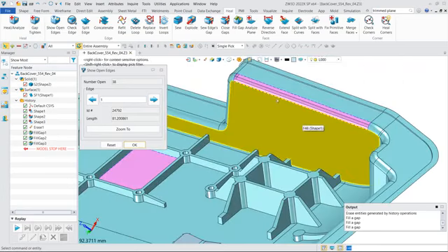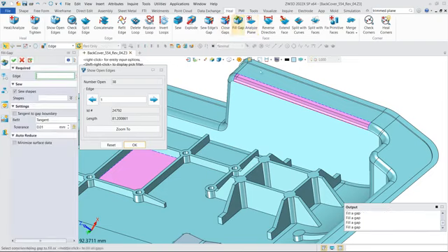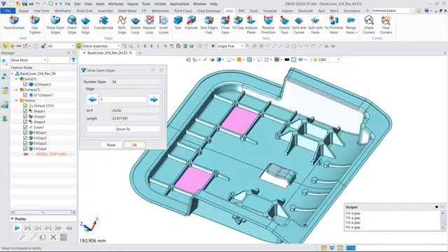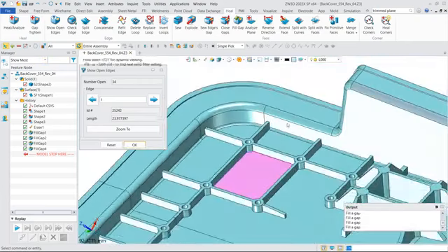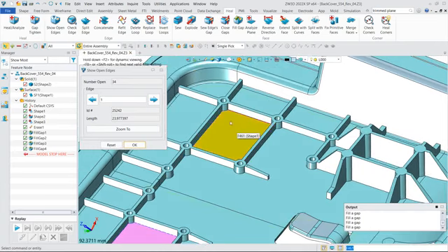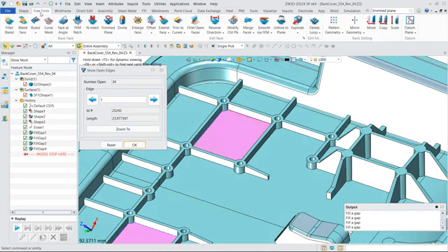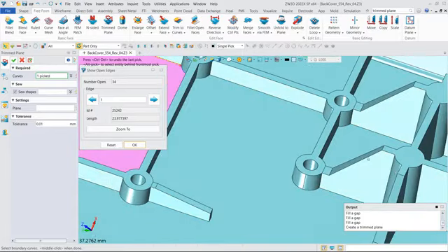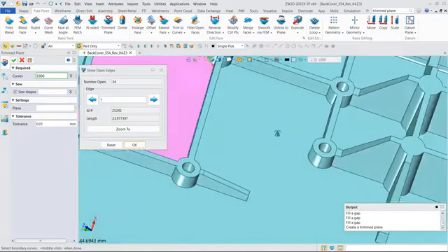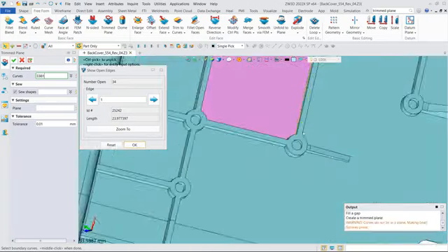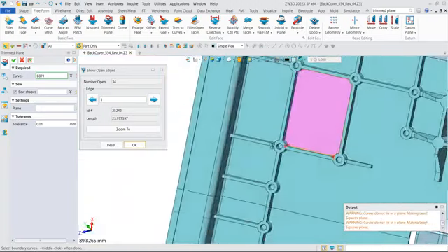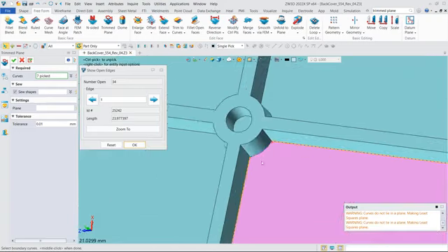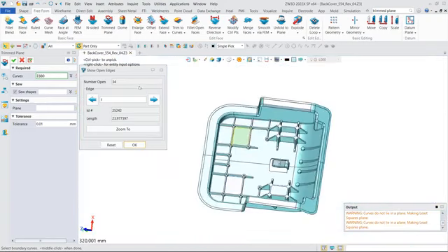For this one, we also use the fill gap. Apply. And for this broken area, we can use the trim plane. We need to go to the freeform tab. We use this function, trim the plane. And we select it and select the edges. We apply OK.